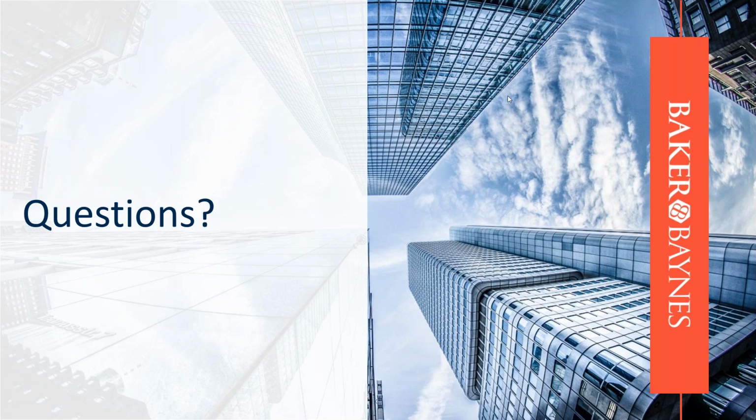Okay, so there's a question here. It's actually a very good question from Nicholas, saying, hi, do the PDFs have the same program function as an image, only background or foreground setting? No. Actually, you can use the PDFs to take certain things, like if you get a PDF from a sub-consultant with a floor plan, as an example, you can bring that PDF in and make it an active item where you're able to dimension straight off of the PDF, as long as the scales and everything are obviously the same. So it's a very useful tool to do that with as well.